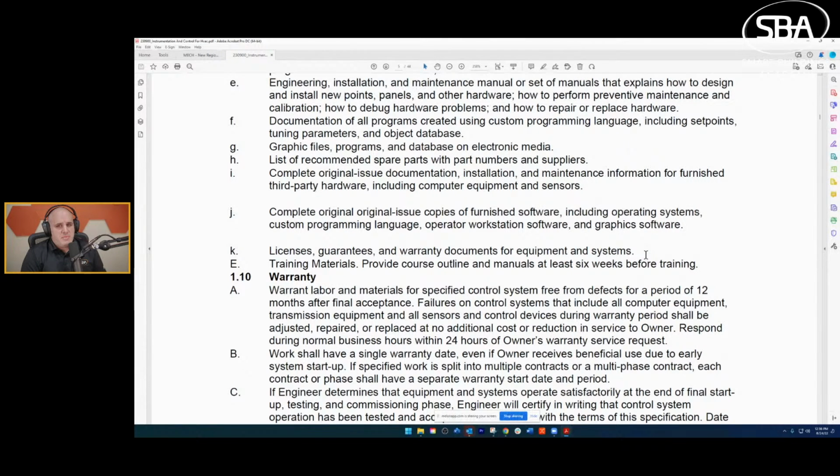If it's a representative points list, you then can take two schools of thought. If this representative points list, you're maybe on a design build job, and this is during the SD or the DD phase, then realize that's representative. And as the equipment changes in the CD phase, those points lists may change. If this is 100% CDs, then you very well should accept that that is probably the points that are going to be available.